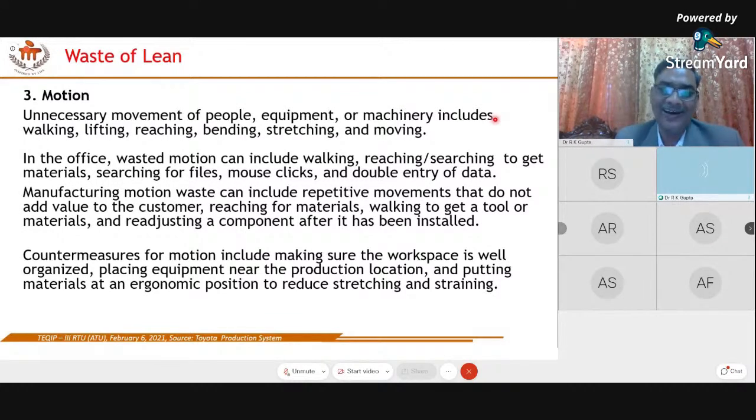But we are arranging our manufacturing facilities so that they can do all the activities of this composite part. Then the production cell for this part family would consist of those machines required to make the composite part. Such a cell would be able to produce any family member by omitting operations corresponding to features not possessed by that part. Right, this is the composite part concept.